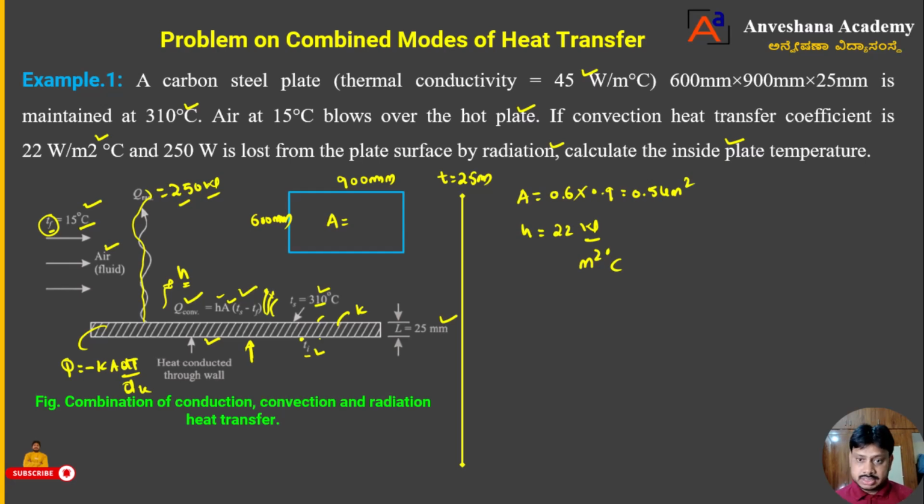Okay, to do this, I will list out the given data now. What is this Ts now? Yes, Ts is equal to how much he has given, dear students? That is 310 degrees Celsius. Fine. Next, the air that is moving he has taken as Tf. Tf is equal to 15 degrees Celsius, that is the temperature of the fluid. Okay, fine. The next coefficient, that is h he has given, that I have already taken.